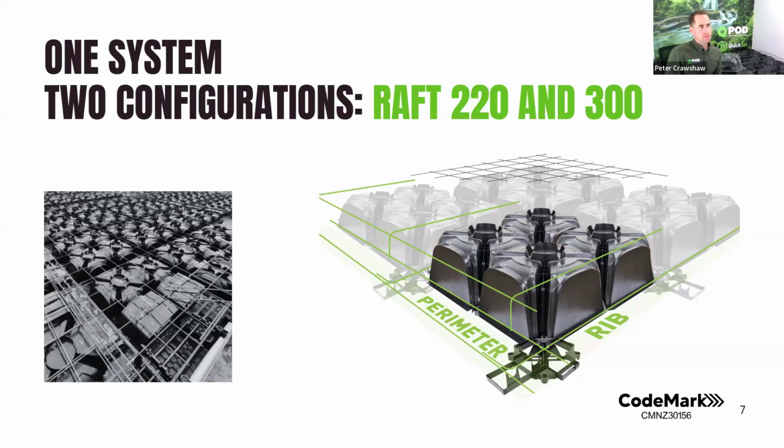Yes, and I did cover that slightly, or you might have picked up when I was mentioning the stirrups and the fibres. So when we get into M and E class expansivities or reactive clays, we often see the use of extra shear steel required. Obviously, firstly, you'd be putting more steel in the reinforcing and in the mesh, and then extra to that, you may need to go to the extent of putting stirrups or fibre in. The latter being by far the most preferred option by all.